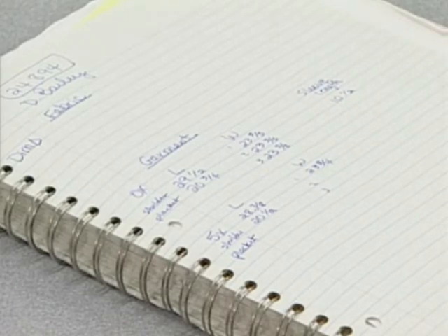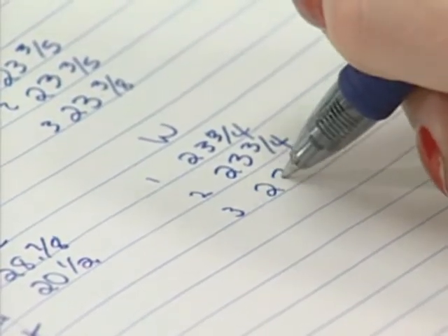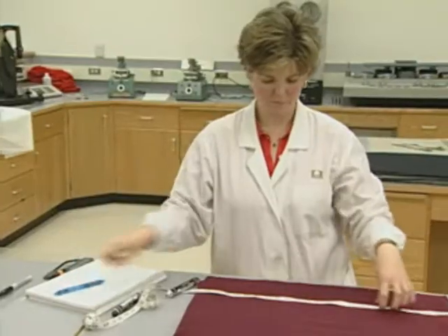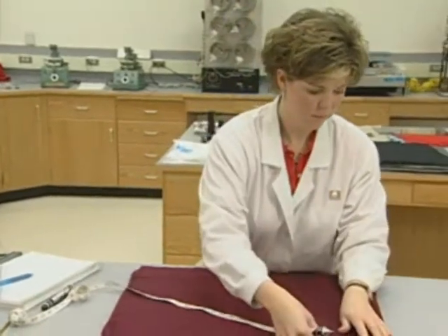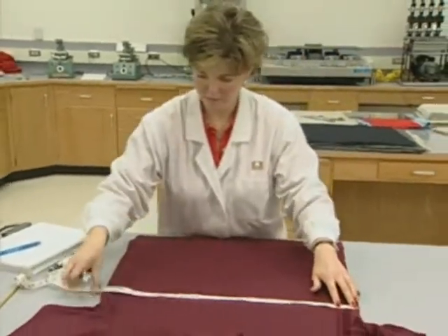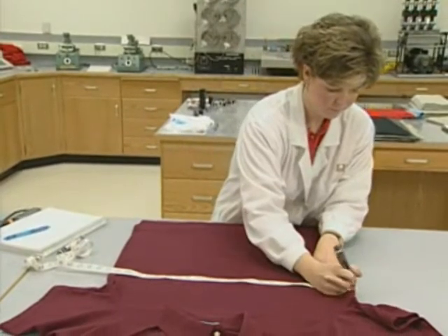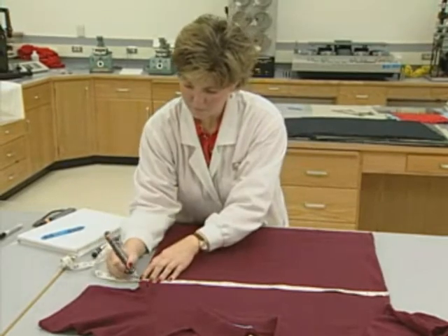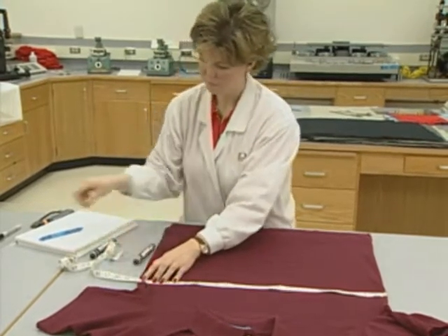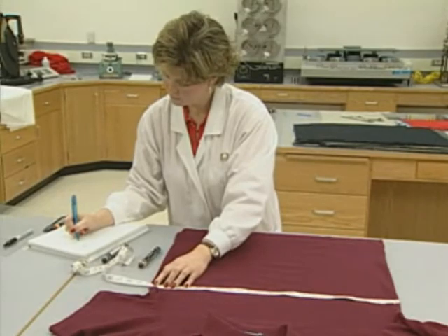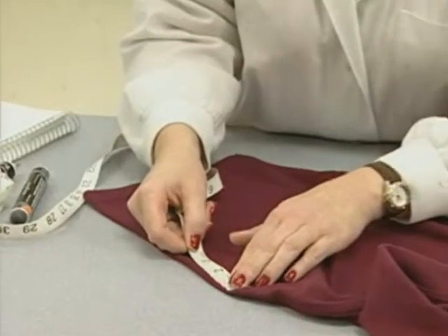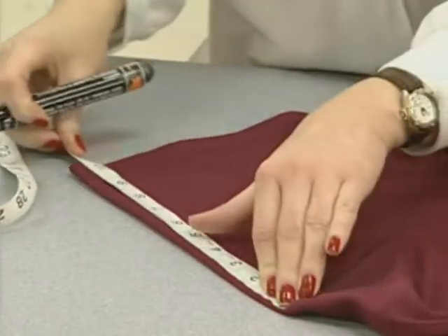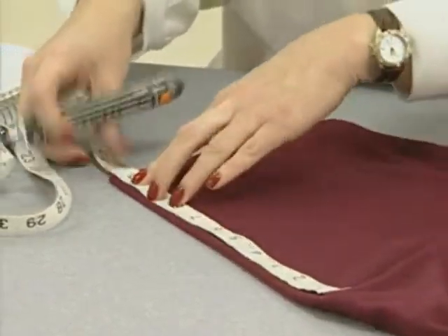The value should be reported as an average percent dimensional change to the nearest 0.1% for each fabric direction. As mentioned, garments are evaluated for shrinkage with a slightly modified test format. With garments, the determination of dimensional change is based on the location of benchmarks. This is important because garment construction, sewing threads, sewing tensions, and trim may affect the fabric and garment dimensions. Therefore, predetermined and agreed-upon benchmark locations are used. These are covered in detail in AATCC Test Method 150.